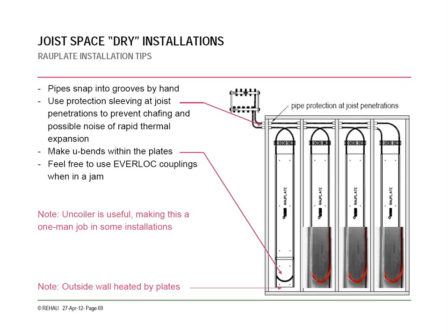As you can see on the top portion of this, all the piping has to get run back through to where the manifold is, which is the case of all layouts, but these tails aren't taking up floor space, which they will typically do in a regular installation.